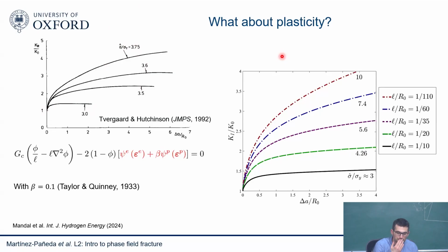But the key point here is that when you are dealing with an elastoplastic material, the value of L matters. Before I said, okay, if you're dealing with a linear elastic material and you have a very large crack, then maybe you can take an L value that is more convenient for your mesh purposes, because fracture is going to be toughness dominated, fracture energy dominated, and therefore you don't want to use the real strength, because that might require using a very small length scale and a very fine mesh. You want to do the calculation fast, and you're going to get the same result. Your result is not going to be very sensitive to L, so you may as well change L a little bit. If you do that in plasticity, because the crack growth resistance, the R curve, is going to be dependent on your plastic dissipation, it is going to have an effect.